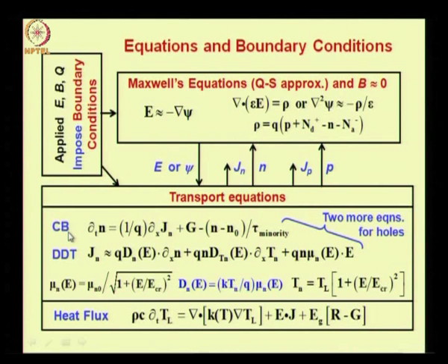So when we use the drift diffusion thermoelectric current approximation, we absorb the balance equation result into this expression for the electron temperature and we use a field dependent mobility.